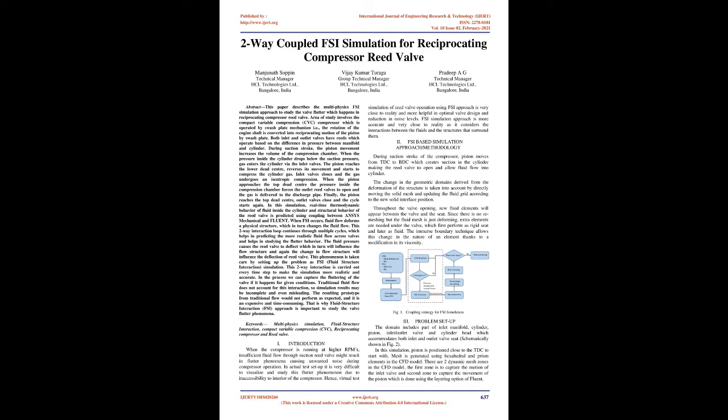When the piston approaches the top dead center, the pressure inside the compression chamber forces the outlet reed valves to open and the gas is delivered to the discharge pipe. Finally, the piston reaches the top dead center, outlet valves close and the cycle starts again. In this simulation, real-time thermodynamic behavior of fluid inside the cylinder and structural behavior of the reed valve is predicted using coupling between ANSYS Mechanical and FLUENT.